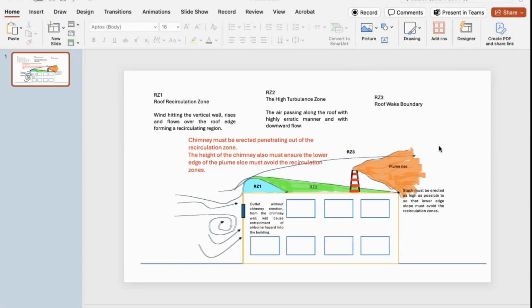Now, a chimney and stack requires, I wouldn't say rigorous, but a methodological approach in designing. Unfortunately, there is this very basic rule of thumb that a chimney has to be 3 meters above, and certain distances must be required and all that. This rule of thumb is good, but using it without actually understanding the function of a chimney defeats the whole purpose. First of all, we must always understand the fundamental function of a chimney.